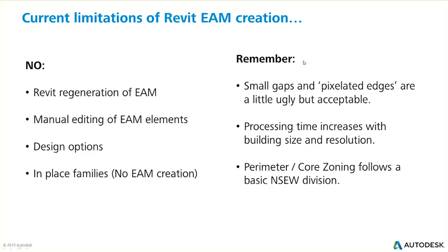Remember, I mentioned that processing time increases with building size and resolution, so we would recommend trying this for the first time on something small or a test model, so that you understand how it's working, and then work your way up. As I said, we've applied this to very large models, but you just need to know how it behaves. You don't want to lock out Revit for an hour, waiting for it to return.